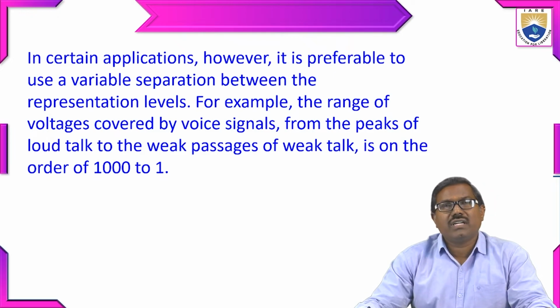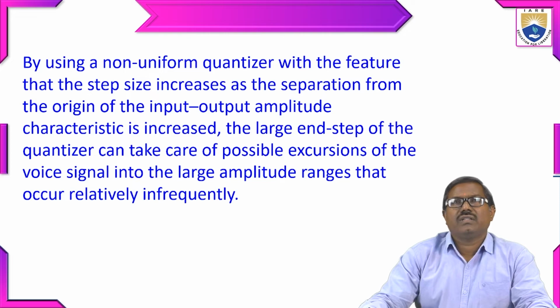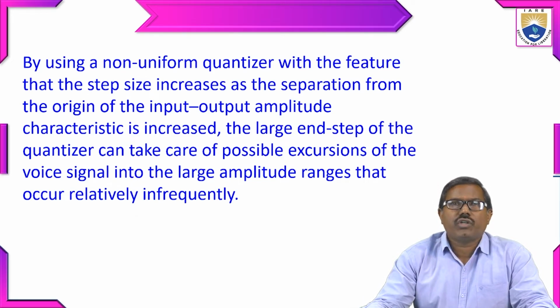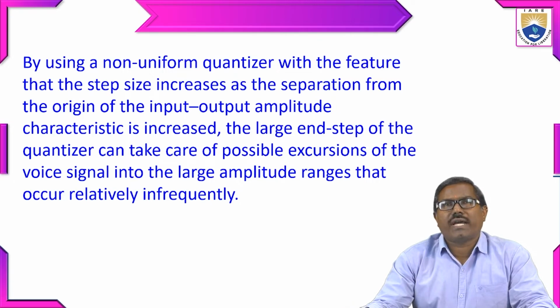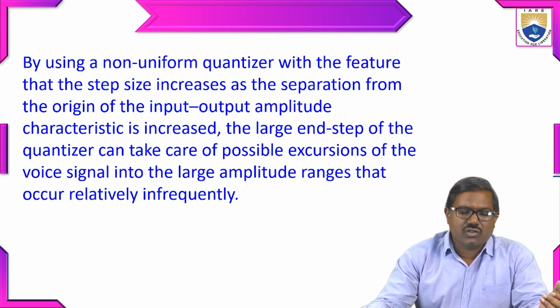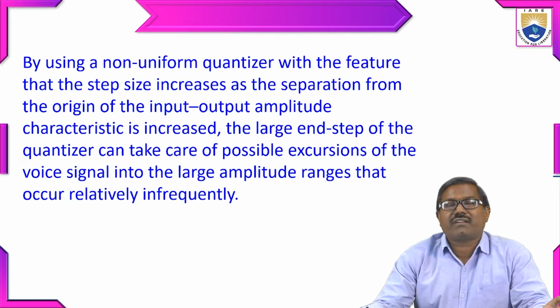So here I am going for non-uniform quantization. By using a non-uniform quantizer, with the feature that the step size increases with separation from the origin of the input-output amplitude characteristic, the large end steps of the quantizer can take care of possible excursions of the signal into large amplitude ranges that occur relatively infrequently.